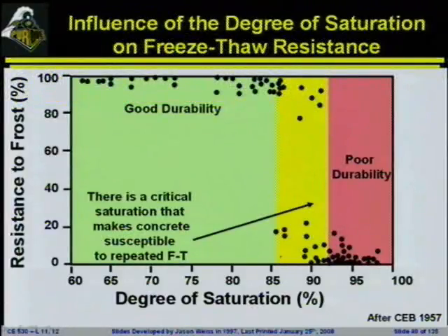All right, a couple things that you need to remember for freezing and thawing. Air entrainment is incredibly important, and we will talk about that. And I don't want to minimize air entrainment, but there are a few things that have to come together for freeze-thaw to be a problem. It's kind of like one of these issues of the perfect storm has to be brewing. You can't have freezing and thawing damage in the Keys of Florida because it doesn't freeze. So it has to get to a cold temperature.